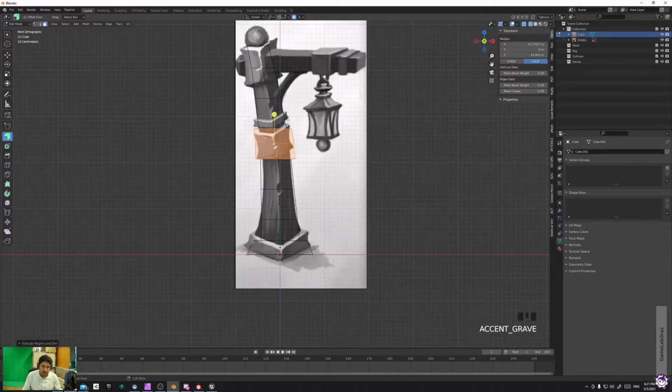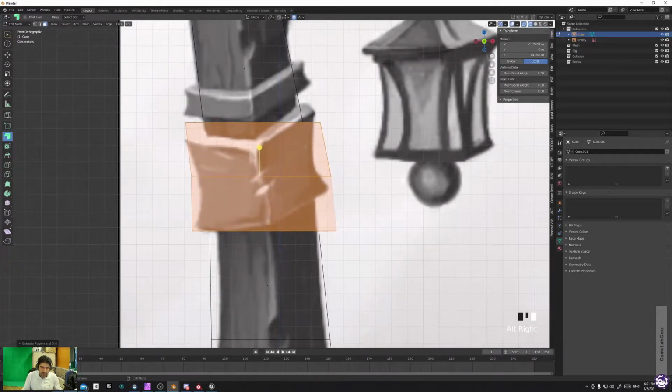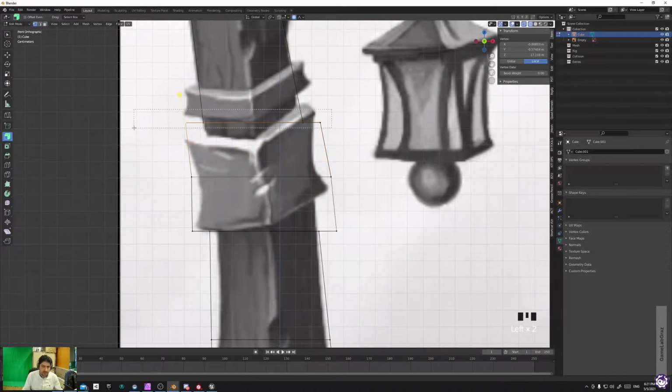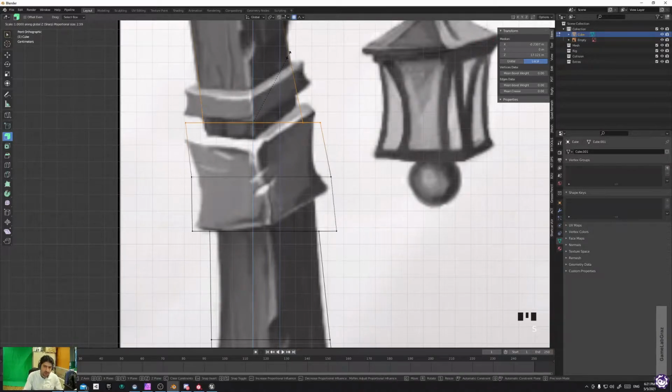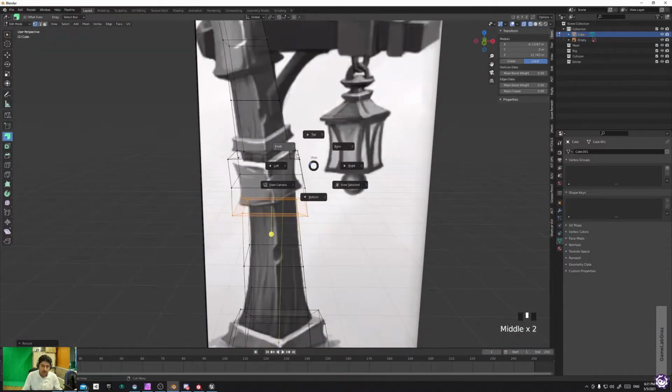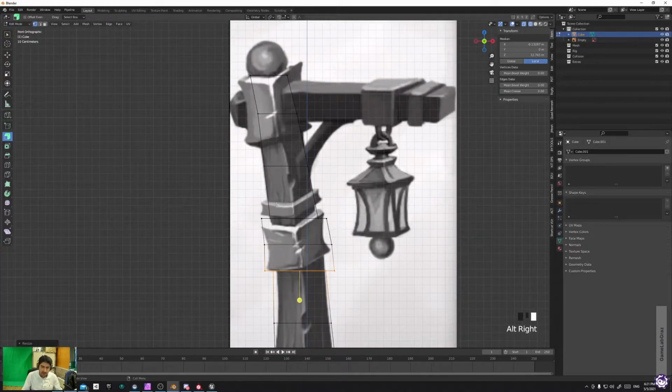Usually, when you use this tool, you should be careful that all of your vertices stay in the same line. For example, if they are going a little bit higher, in this case, I select all of them and scale them in the Z direction to the 0 value. Sorry, I should deactivate this tool first. Scaling to the 0 value, I can fix them on the same line. Okay, perfect.